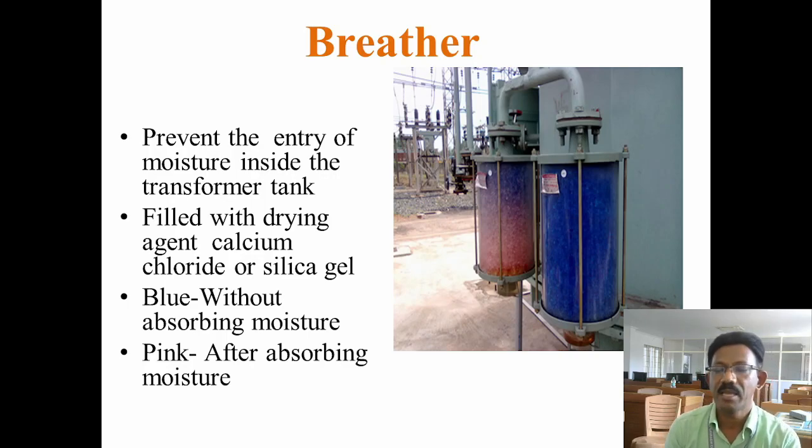The given image has two breathers. One is in blue color, another one is in pink color. Normally, before absorbing moisture, the silica gel looks blue in color. After absorbing, it is in pink color.